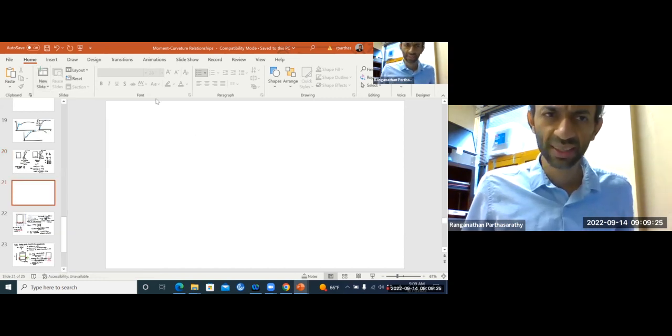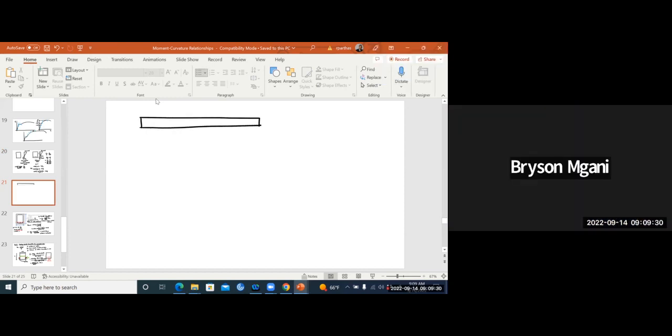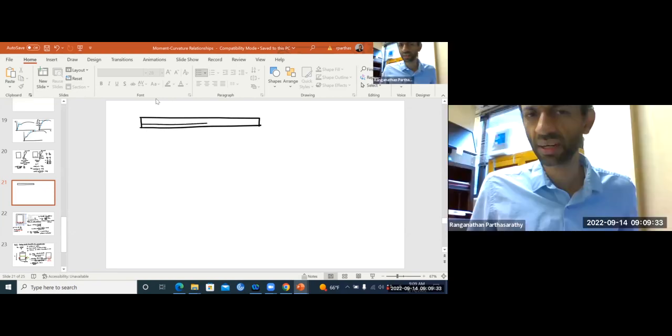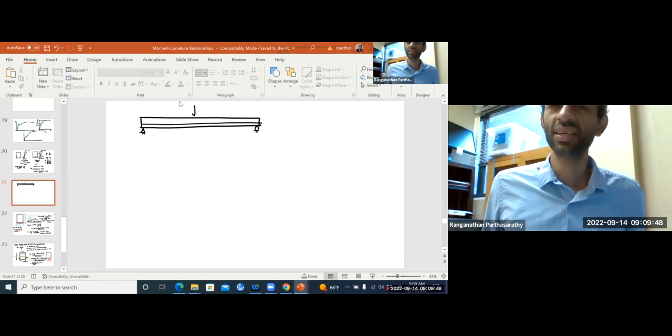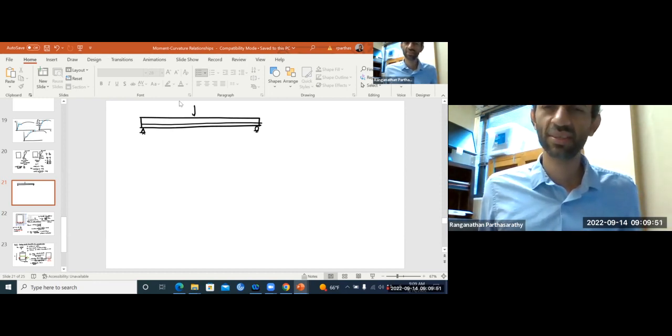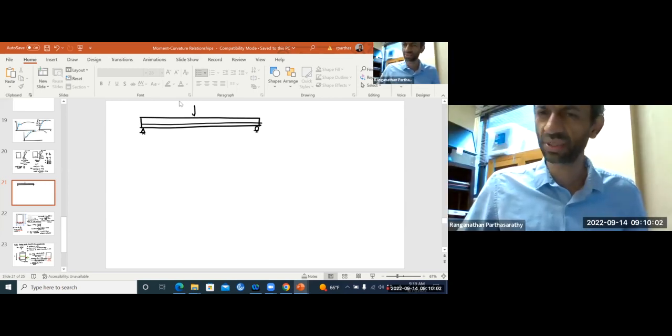Bryson, see, this is a beam, right? A concrete beam, and here is your rebar. Now, when you load it, you want ductile failure. In a building, when it reaches the ultimate load, you don't want it to break like glass, right? Then everybody will just lose their life. You cannot do any evacuation. Everything will just collapse like an explosion.